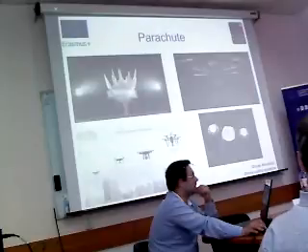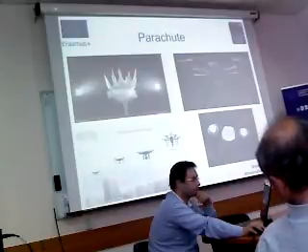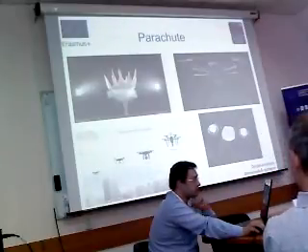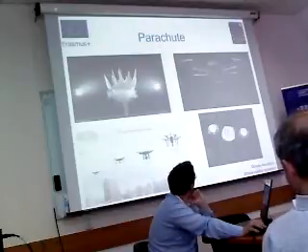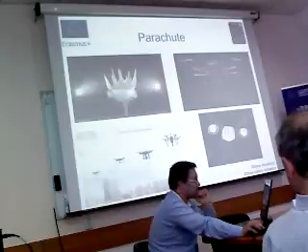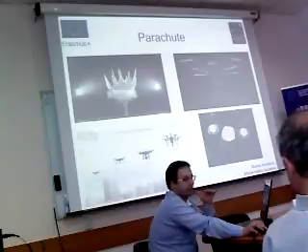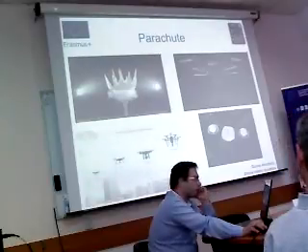And I can show you some examples. This is an example of the SafeAir pyrotechnic parachute recovery solution. It clips on the top of the drone, and it automatically deploys when free fall is detected by a built-in chip.